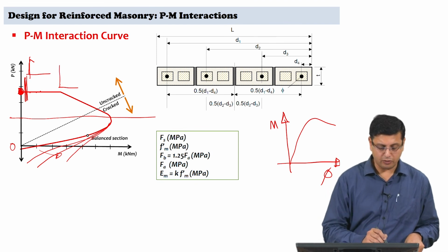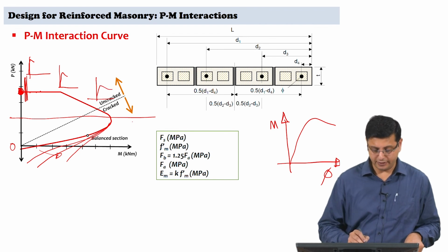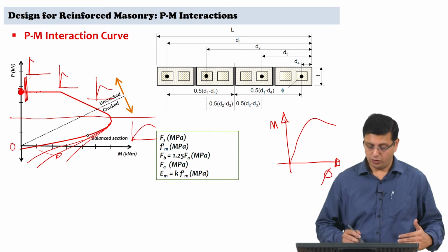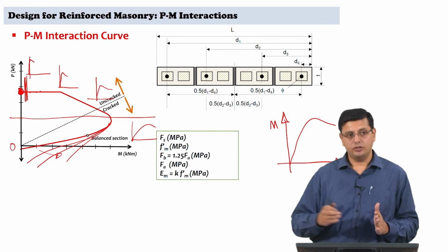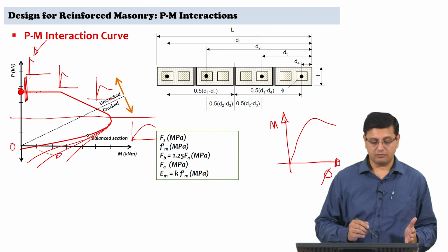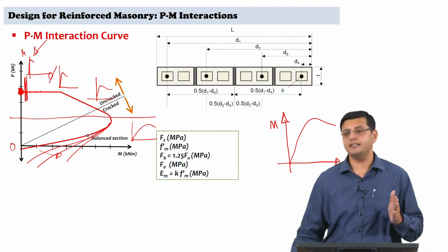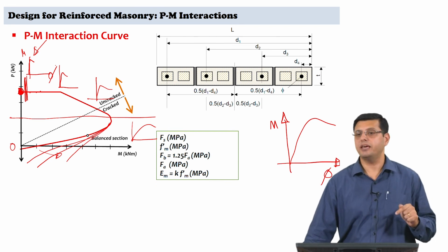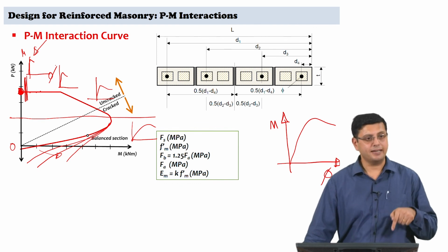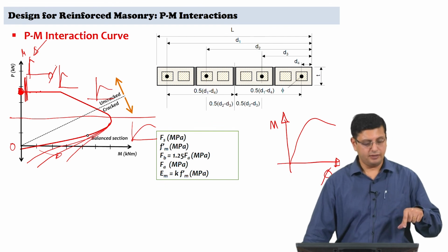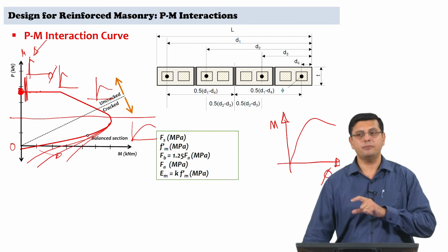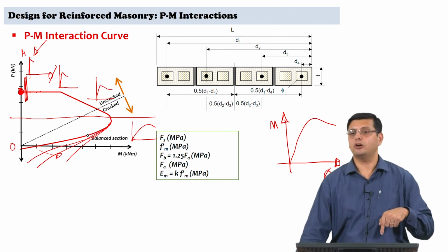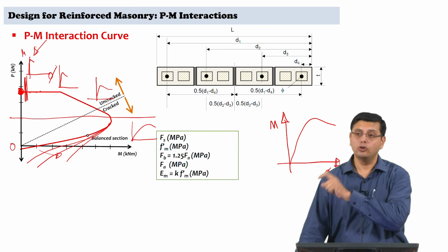As you come down, the moment curvatures will show better ductility, and when you come to the zones in which the axial stress ratios are low, the moment curvature will show good desirable ductility. So, this situation for moment curvature with very low ductility does not guarantee good ductile performance as far as earthquake resistance is concerned. When axial stress ratios are high, you do not get ductile behavior how much of a steel you want you put in there. So, as a typology, masonry, because of load bearing walls, gives you the possibility of low axial stress ratios. Therefore, you are in a PM interaction zone where moment capacity increases because of the presence of steel significantly, and 2, the moment curvature of the sections there significantly demonstrate good ductile behavior.